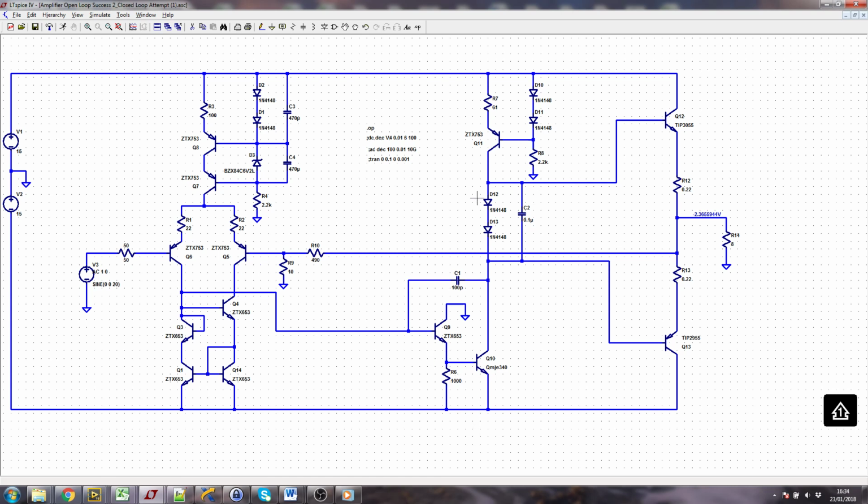It may also be that the biasing is ineffectual in the output stage, and it may also be that the feedback resistances are too small. So we would change the feedback resistance. The other thing it might be is that the base current leaving Q5 flows through R10 and into effectively the ground, because this is only 8 ohms. Although this is 10, which is probably what's really involved at the minute. And there's 50 ohms here.